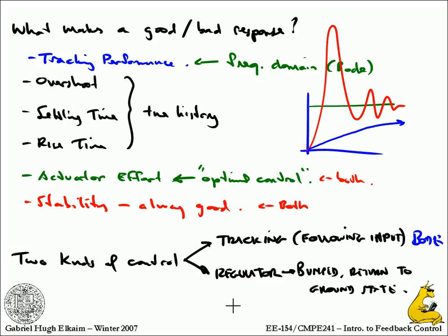Right. They do both, but this is why, for instance, altitude hold is incredibly important. If the plane underneath is drifting upwards and the plane above is drifting downwards, bad things could happen, right? So regardless of what's happening in the atmosphere, you want them to stay dead nuts on whatever you've given it.